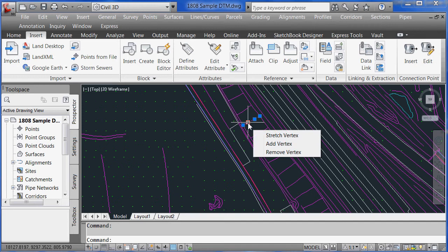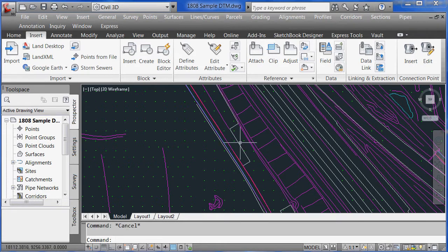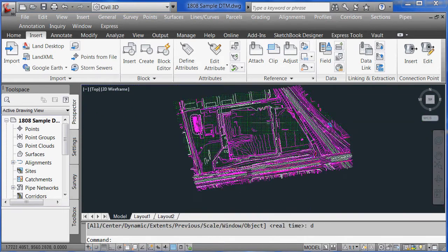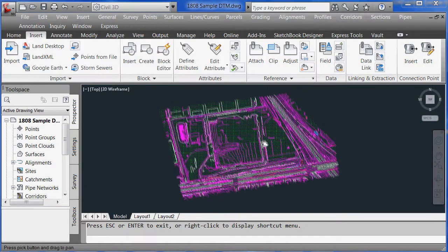I have the northing, or I'm sorry, the easting of 18,127.81, and then the northing is going to be 929 point. These letters are small, so I'm having trouble reading them. But right at the tail end there's an elevation of 805.9790. If you look at one of the other vertices, the elevation changes along with the northing and easting. So that's the proof to let you know that these polylines are in 3D space.